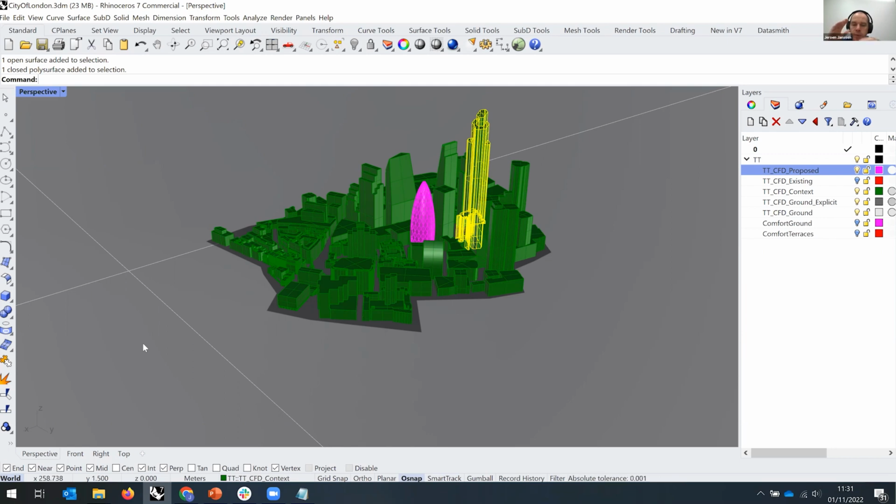So it's the size of that building, and there's a blockage ratio, because basically you don't want to block too much of the airflow so that you artificially squeeze the flow between the buildings and the top of your tunnel. Because it's still a physical boundary. The CFD simulation takes into account that it is actually an infinite size, but it's still a wall, let's say. So you need to avoid that they're too close. If we're going into the low res and the medium res, to be honest, we're squeezing it a little bit. We're going down to 3 times that height. So the tunnel becomes smaller.